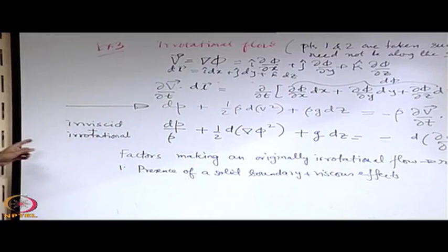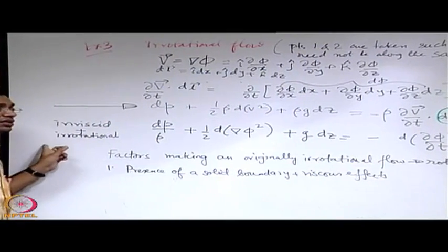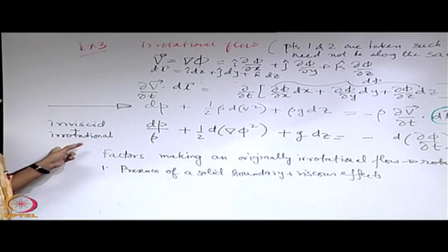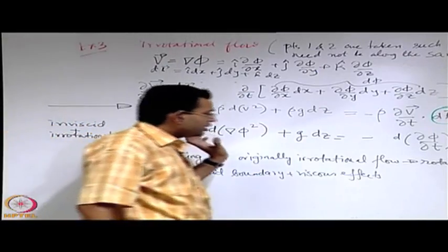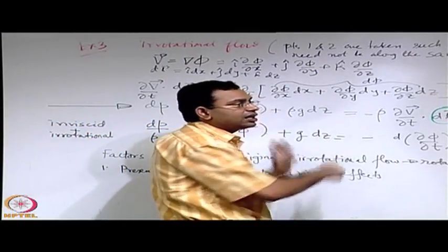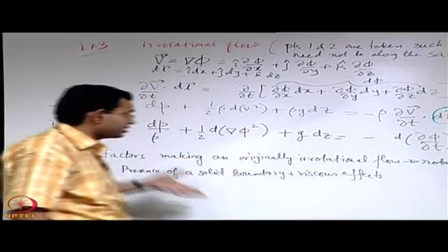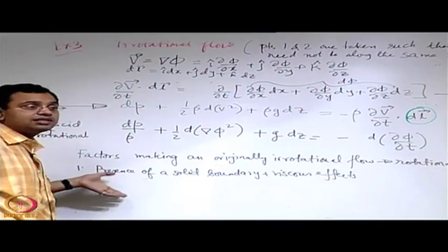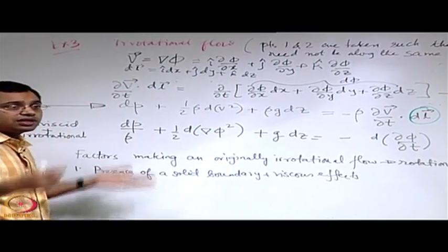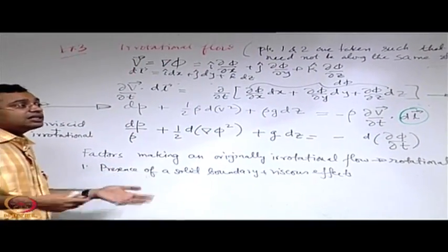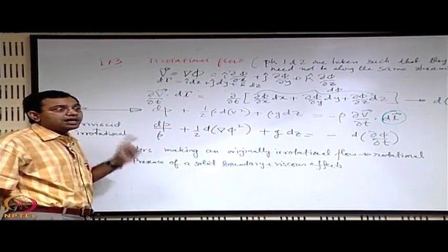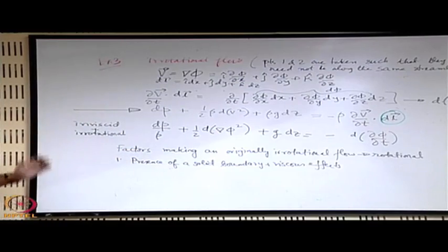Although you may start with an irrotational assumption, the viscous flow assumption will not hold that irrotational state physically. We will see that mathematically it will not be able to reflect this directly at such an elementary level. It is possible to look into that mathematically, but physically we have to at least appreciate that if it was irrotational, there is no guarantee that eternally it will remain irrotational, and one of the factors which disturb that irrotationality is the viscous effect in the flow, the presence of wall boundedness.